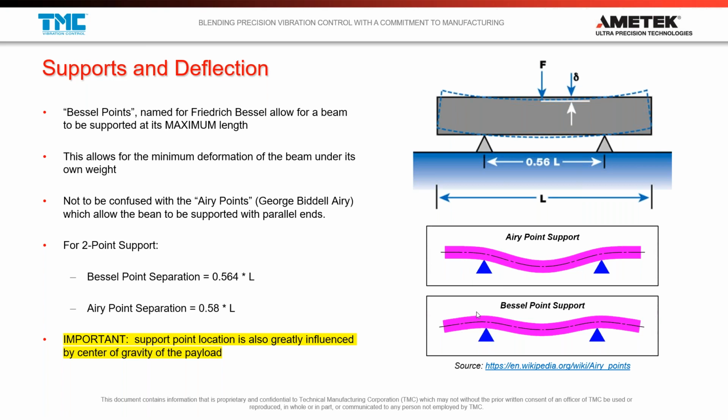So when you work with TMC or really any manufacturer of tables, and you're trying to figure out how to configure your support structures, it's really important to look at your payload. And if your payload has some high center of gravity items or high-mass items on it, you're going to want to think about where you're locating your points.